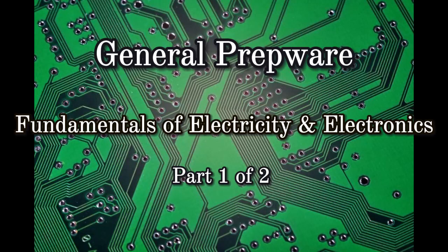Capacitors are sometimes used in DC circuits to smooth out slight pulsations in current/voltage. A 14-ohm resistor is to be installed in a series circuit carrying 0.05 ampere. How much power will the resistor be required to dissipate? At least 35 milliwatts.